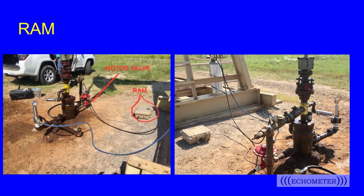But one of our criteria for determining if it's static out is when things stop changing. So maybe we know in an area that it takes 3 days or 5 days for a well to reach static bottom hole pressure. But if we don't know, we're going to want to measure several fluid levels and track it. And when they stop changing, we know we're at the static or approaching the static. And if the well is a distance from us, that might be a problem to have to travel out to the well and shoot liquid levels on a regular interval.